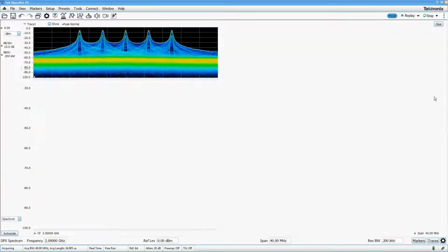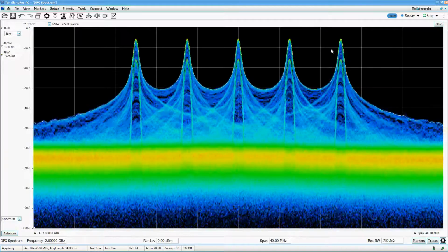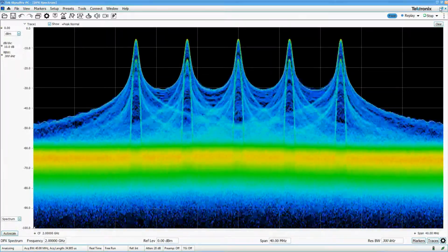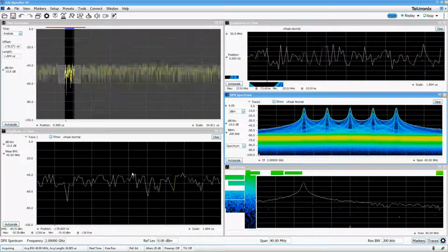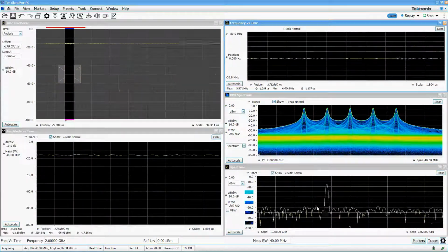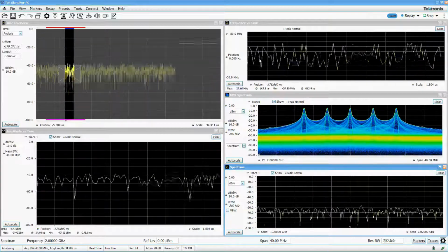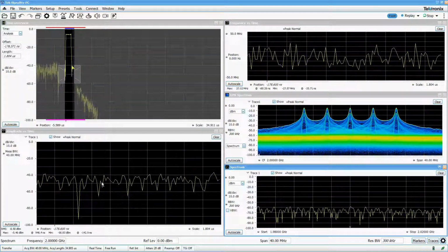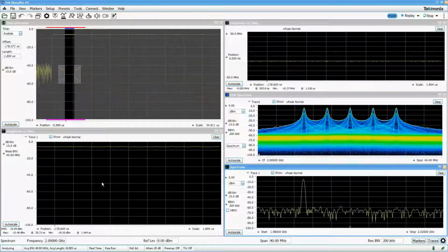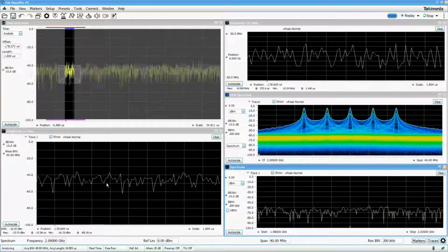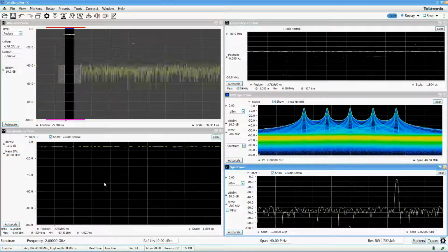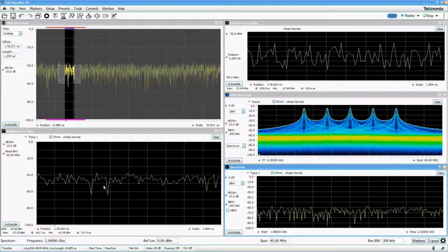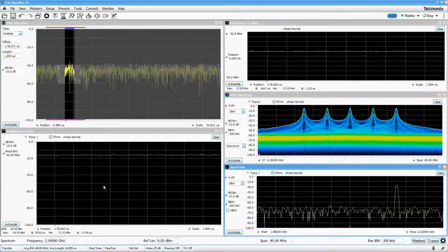On the real-time display, we can see that the signal does not have a constant frequency or amplitude. Let's capture a stable signal and I'll give some examples. Notice our signal is jumping all over the place in both the spectrum display and all the time domain displays. This is because the analyzer is in free-run mode, where it just captures and processes data as fast as it can without reference to the presence of signals. We can use a trigger to stabilize the acquisition based on certain signal characteristics.